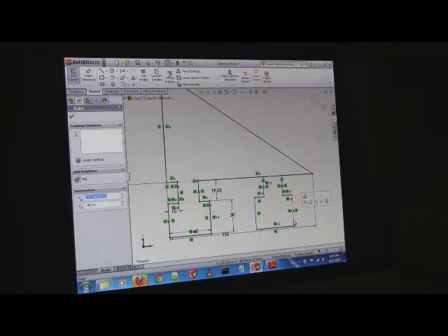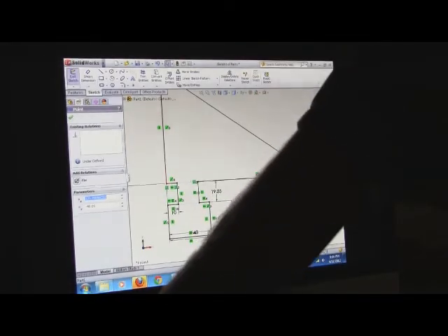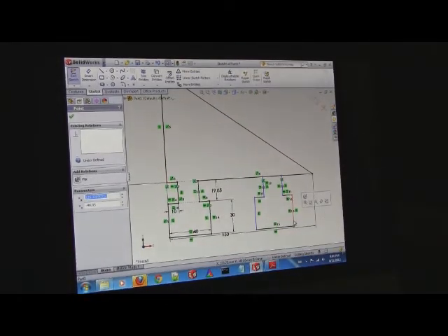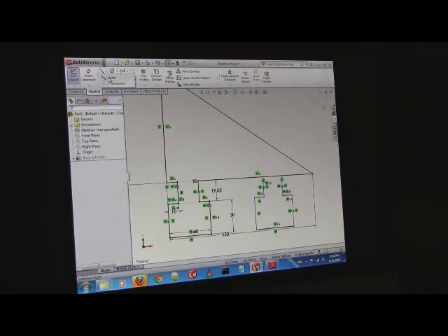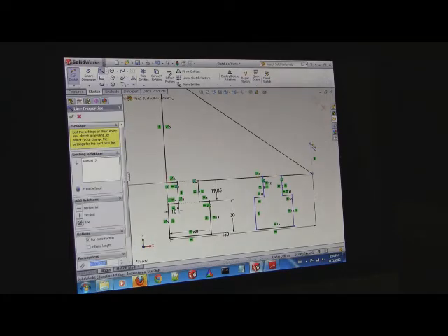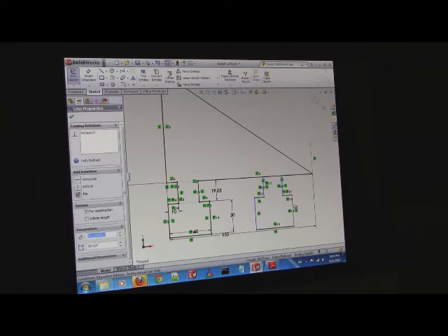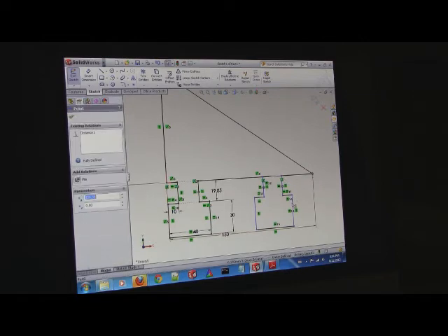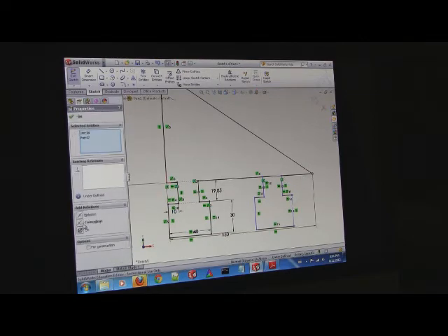Okay. So, remember how we did the collinear trick to line it up? There's a version of that for a line and a point instead. On the right, eyes on my screen, you see this point here? This is all we've got to work with in terms of lining it up. There are two ways we could go. We could put a center line here and use the collinear trick between this and this, but that's sort of a pain. Click this point, click this line, and hit coincident. Boom! The point doesn't actually have to physically be on the line segment, just on the theoretical line through that point.